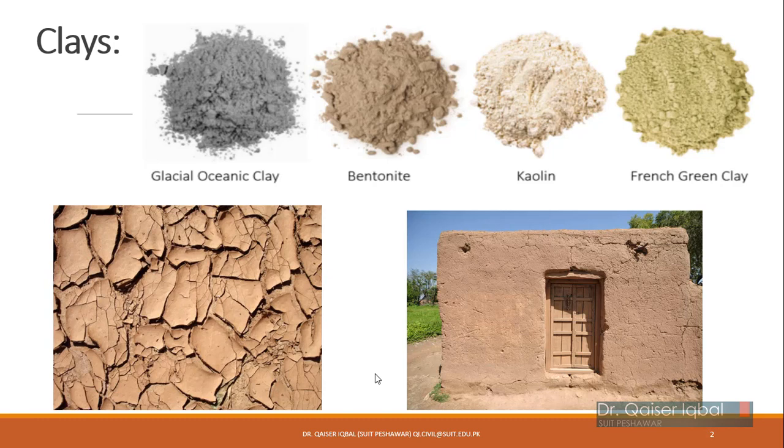And we discussed that they are basically formed by mechanical weathering of their parent rock. Because they are inert, they don't carry any charge, so they have no affinity towards water, so they are not plastic, and they cannot be molded into shapes, and their strength is more than the clay. Clays, however, we said that we will discuss later.